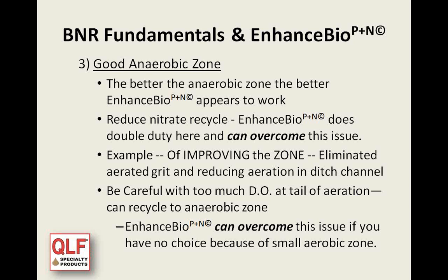We can overcome nitrates because that's how we denitrify in a system that has a total nitrogen limit: we use our product to denitrify in an anaerobic or anoxic zone. And so we can overcome that, but again, it takes more product. So it's a matter of having either good operations or well-designed plants to minimize the use of our product.